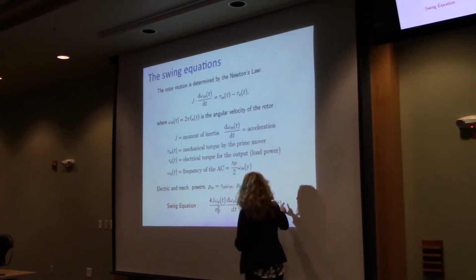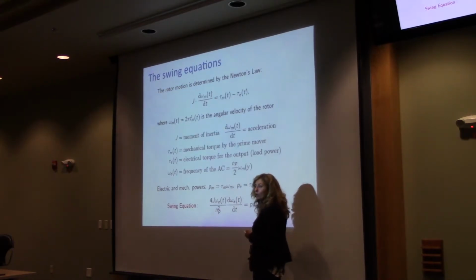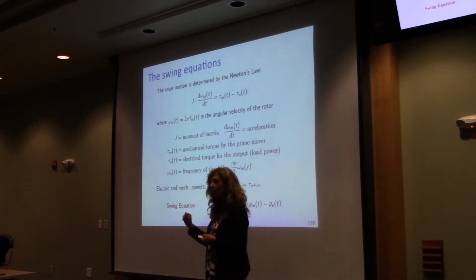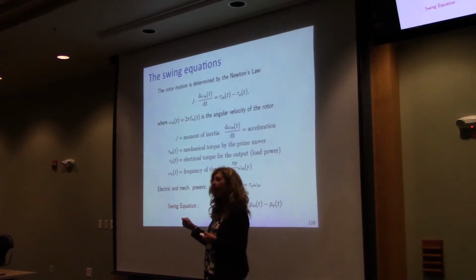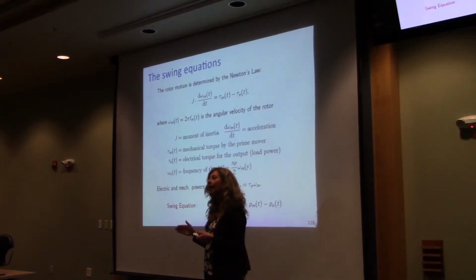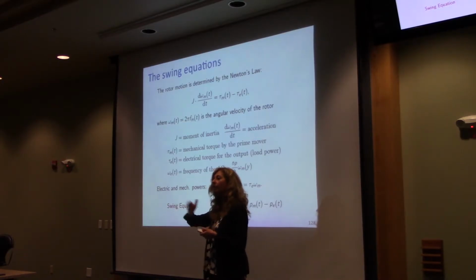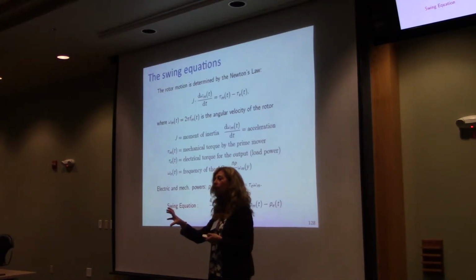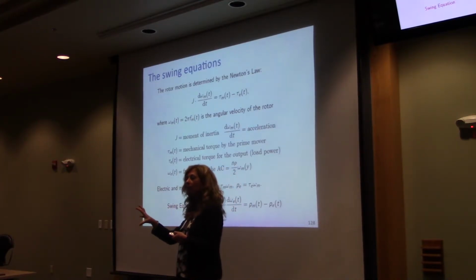You can't put just a simple control signal in this single equation by observing electrical and mechanical quantities that will solve the problem. Even though it's kind of deceitful, you think you have to just measure locally what is the electrical power and then compensate. You actually can create slow oscillations among different machines. So you don't want to do that. So there are governor controls that try to keep this frequency stable, but it's very much understood that you cannot rely only on those to balance the system.